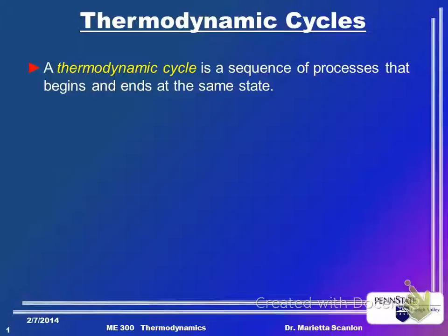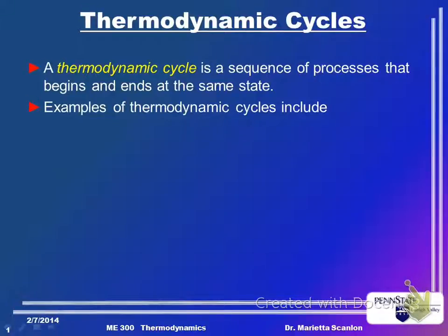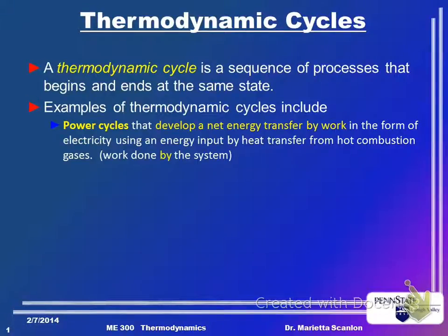So in very general terms, we talked about thermodynamic cycles as a set of processes that start and end at the same state, okay? So if, for example, with three paths, if the properties at state 3 are equal to the properties at state 1, then we say that it's undergone a thermodynamic cycle, okay? What we're going to do in this section is talk about 3 specific cycles that are given names, not just leg 1 was constant pressure and leg 2 is constant volume, but 3 very specific cycles, okay?